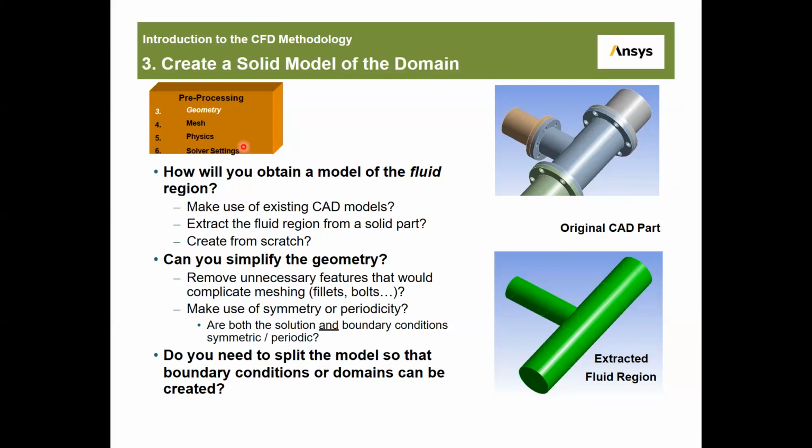I want to analyze this mixing example, the T-joint. Which part do I need to draw? I only want to get the velocity. For example, I want to analyze the velocity at the inlet and the velocity at the outlet. So I just need to draw the fluid region.